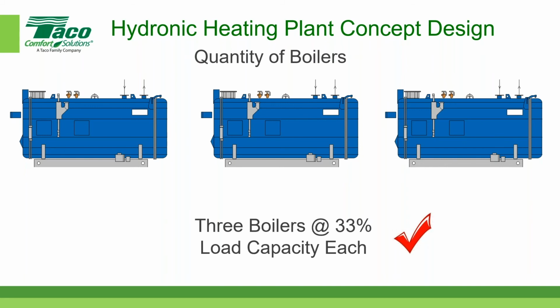Okay. I would think, Rich, that the size of the building would play into this thought process as well, you know? Yeah, exactly. I mean, there are so many variations of boiler sizes and configurations. That's why I recommend you talk to your manufacturer's rep. If you're in New England, for example, the folks at Emerson Swan provide expertise in several lines of boilers, and they can really help you figure out what the best combination of boilers and configurations would be. But for today's discussion, I like the 3 boilers at 33% each.